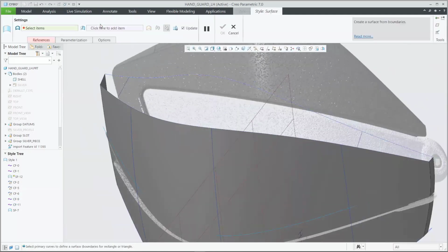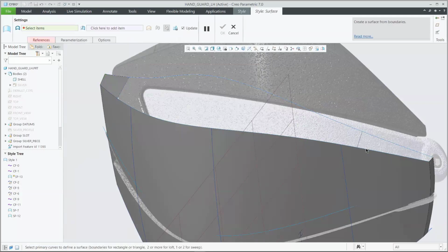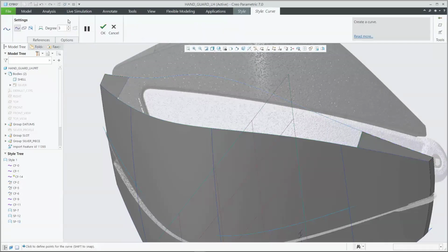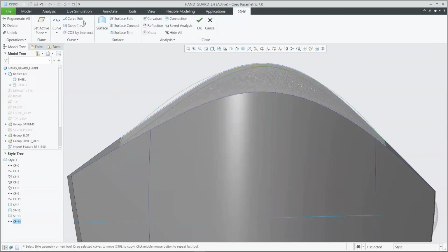So continuing on from the top perspective, I'm going in and still defining my curves. I'm building out the two surfaces for the top itself. It's following that same process, but we can also add capabilities ensuring the tangency, acceleration continuous. We can work with curvature again.